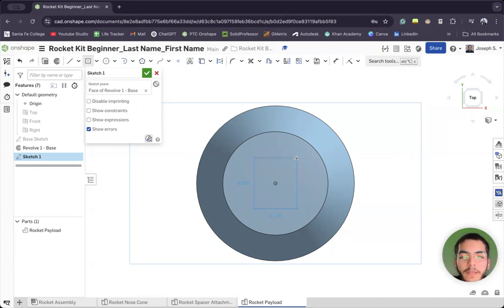So once you press that rectangle and you press once the left click, you can see it creates that blue shape, but you can see this is highlighted, right? It has a white background on it. That means you can actually edit that dimension automatically without having to hit the dimension key. What I mean by that is right now with this being on, I can change the length of this. So instead of 0.485, I can change it to what I want the dimension to be, 0.405.